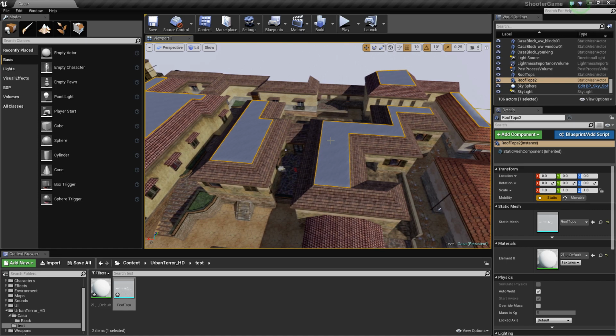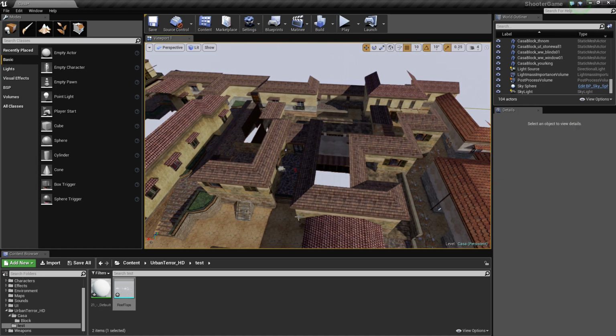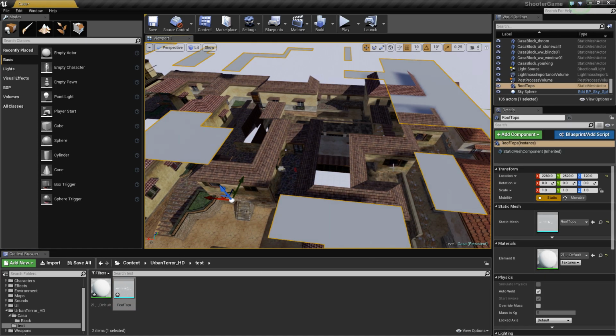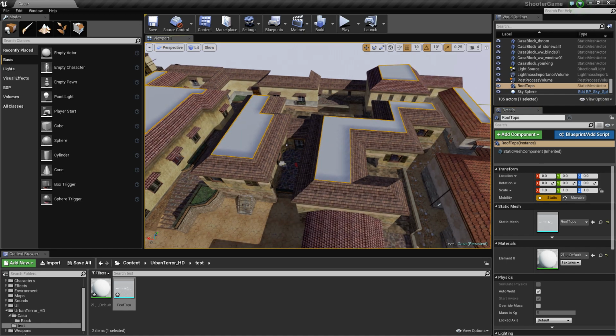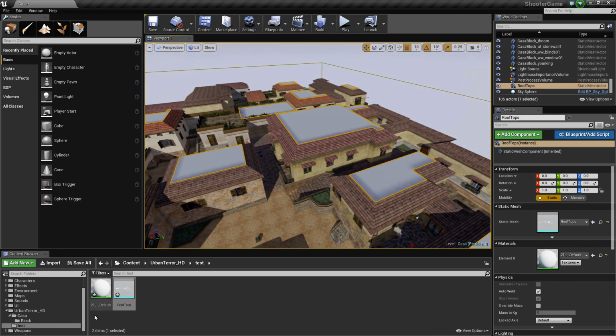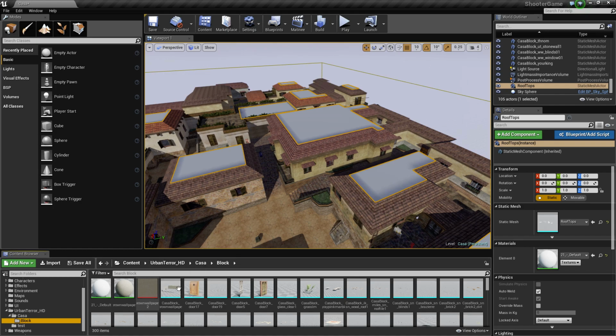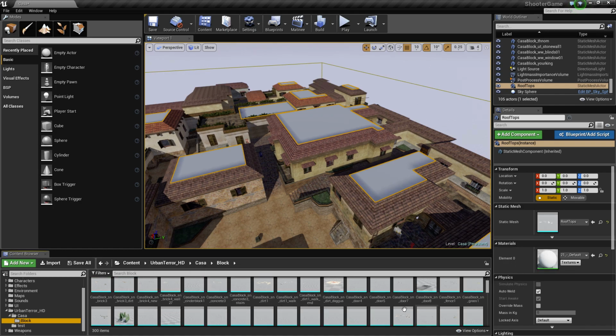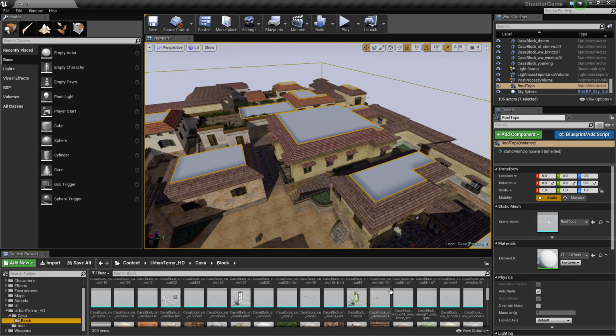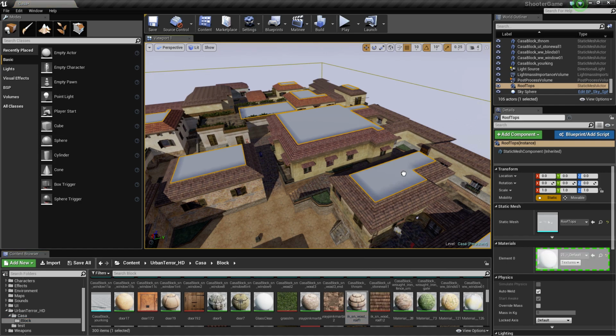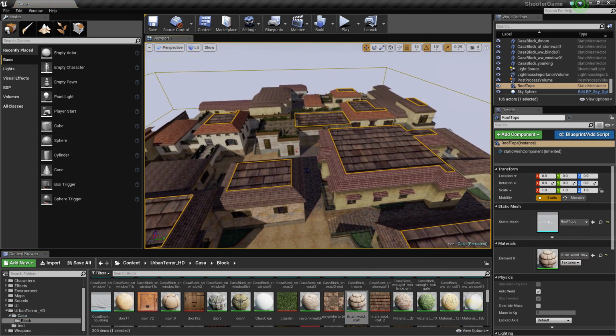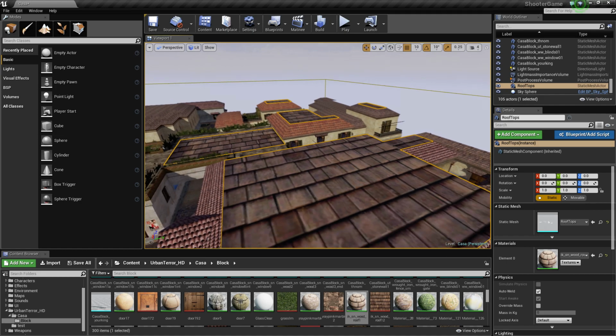Now if we go up top there, we can see there's our rooftop. Let's do this a little bit more seriously, because I already did that. So we're bringing in our rooftop. You can see there it is. It's out of alignment. We just hit the reset, and exactly where it was made in 3ds Max is where it snaps into place. Then we can change the material if we want. Okay, let's find a material, any material. We'll drop that on there, a little wood tiling, and our rooftop is done.